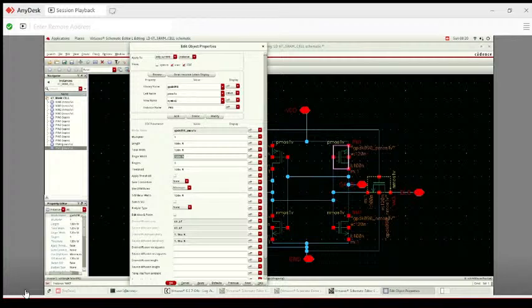So to maintain the pull up ratio, here the access transistor should be 1.5 times of PMOS. So we will get approximately 0.75 as a pull up ratio, which is the width of the access transistor divided by the width of the PMOS transistor, which is 120, equal to 0.75.